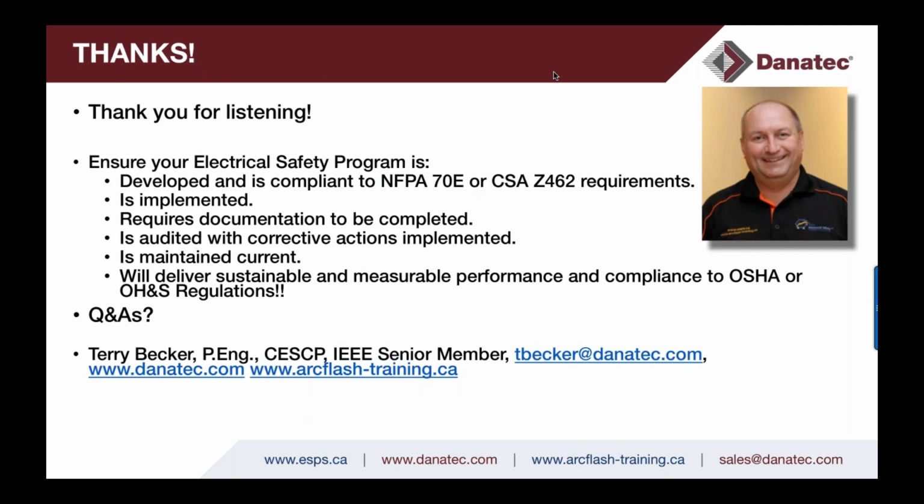Key message here, you should have an electrical safety program. If you don't have one, get in touch with me. Danatec can help you develop an electrical safety program and implement it. The key to solving this problem is through developing, implementing, and auditing an electrical safety program. And every 3 years, when the standards cycle, you update it with these changes, and then you train your workers on the changes of your electrical safety program, and in turn the changes from 70E and Z462. So you do need to train every 3 years at a minimum, generically on 70E and Z462's requirements. And then separately, you need to do electrical safety program rollout training for your company.